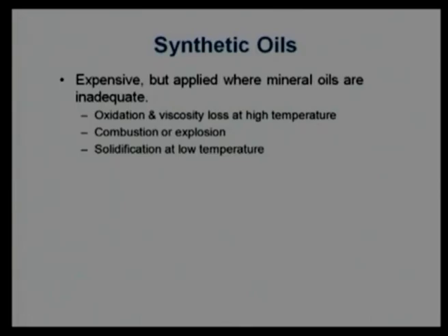And we say that because of the cost, these oils should be used whenever mineral oils are inadequate. Either they have more tendency of oxidation, more tendency of viscosity loss, more tendency of explosion, or more tendency of solidification. In those situations, synthetic oils should be utilized. Otherwise, mineral oils are very cost effective. Those oils should be utilized either in pure form or with some sort of additives to give extra properties.